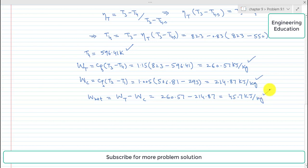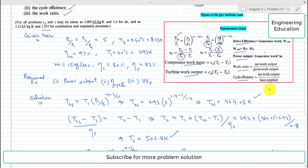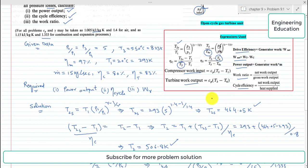Now we are interested to also incorporate the mechanical efficiency or the drive efficiency, and it is equal to generator work divided by net work. So from this, if we find the generator work, we will multiply the mechanical efficiency with the net work.